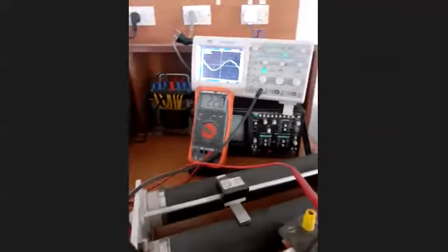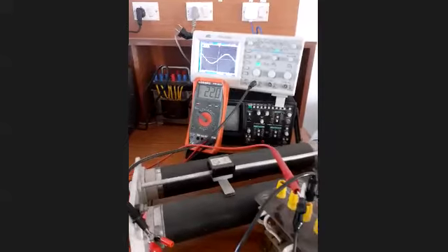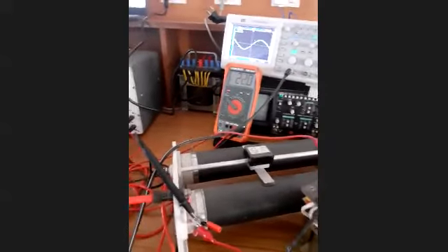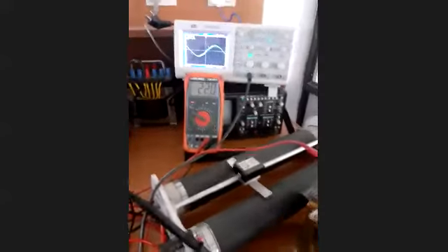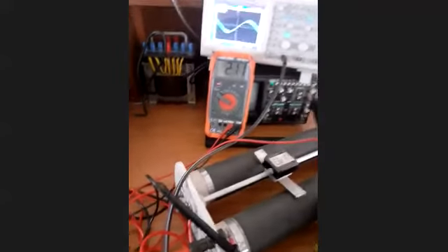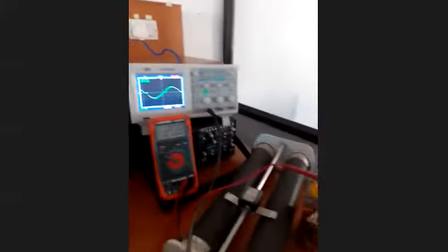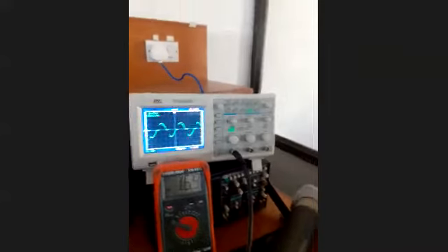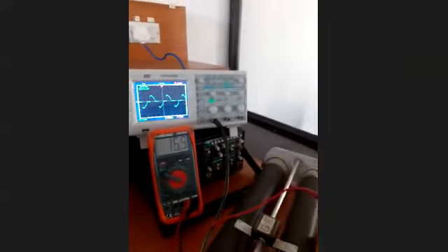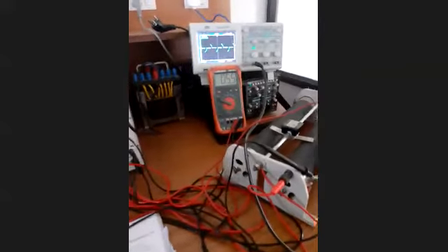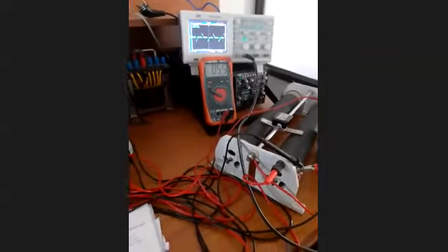So this is regarding the AC voltage controller. You can get any amount of voltage across the load just by varying the firing angle to the thyristors which are connected in anti-parallel, right? So now you can see one cycle. Okay, so forget about these connections. We'll see these connections when you come to the college, right?